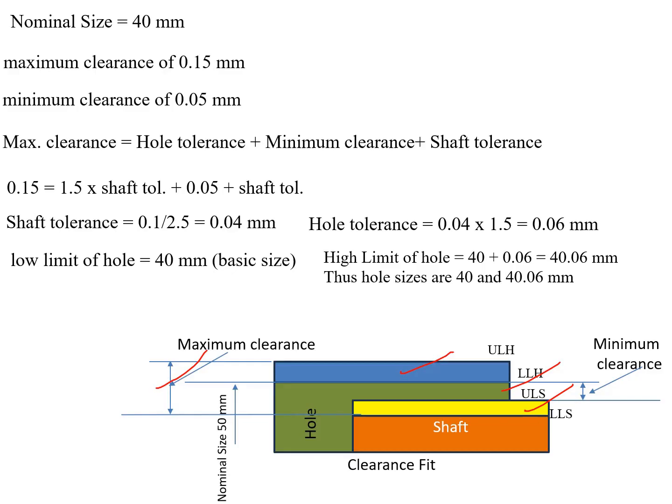Then the higher limit of the hole equals 40.06 mm. So the limits of the hole are: lower limit 40 mm and upper limit 40.06 mm.